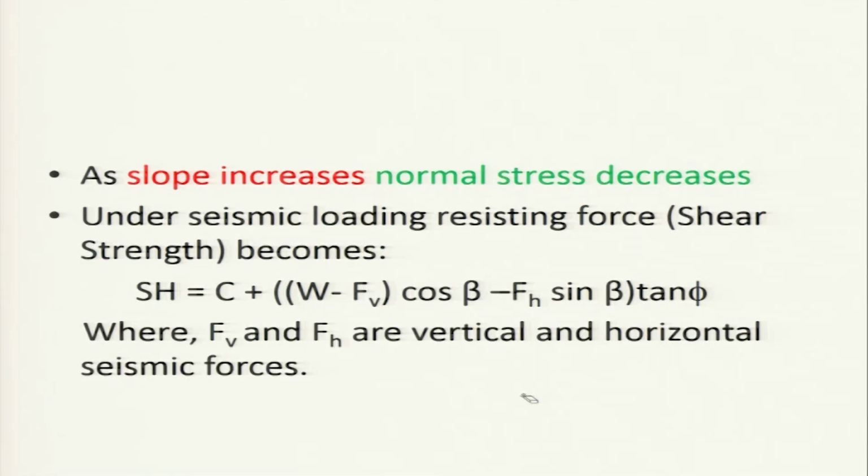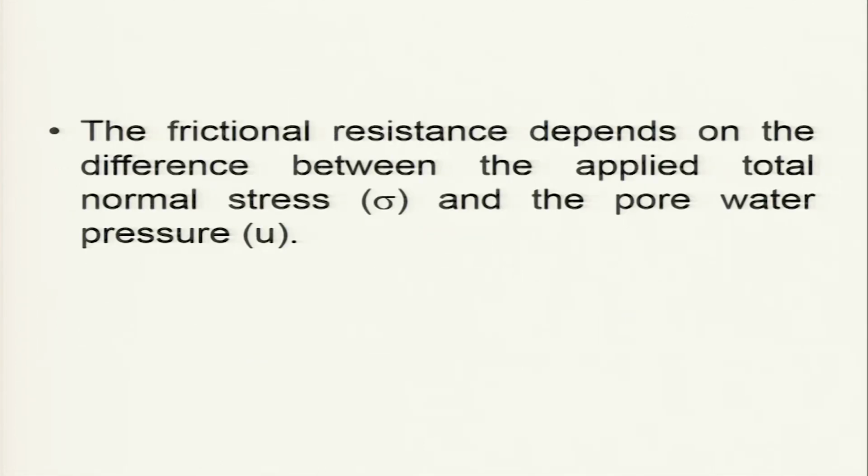So, where Fv and Fh are vertical and horizontal seismic forces. This part you will have to take into consideration when you are talking about the seismic loading. So, the frictional resistance depends on the difference between the applied total normal stress and the pore water pressure.